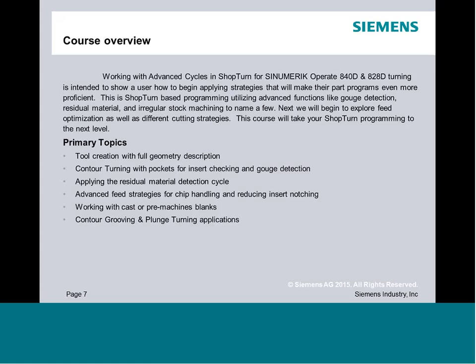From there, we're going to get into contour turning, but specifically contours with pockets, like irregular shapes, like hourglass style shapes. This way you can start to see how that geometry becomes so critical when I send tools into areas that maybe don't fit. We can see the gouge detection, and then from there we'll certainly play around with an option called residual material detection. You'll get a chance to see that.